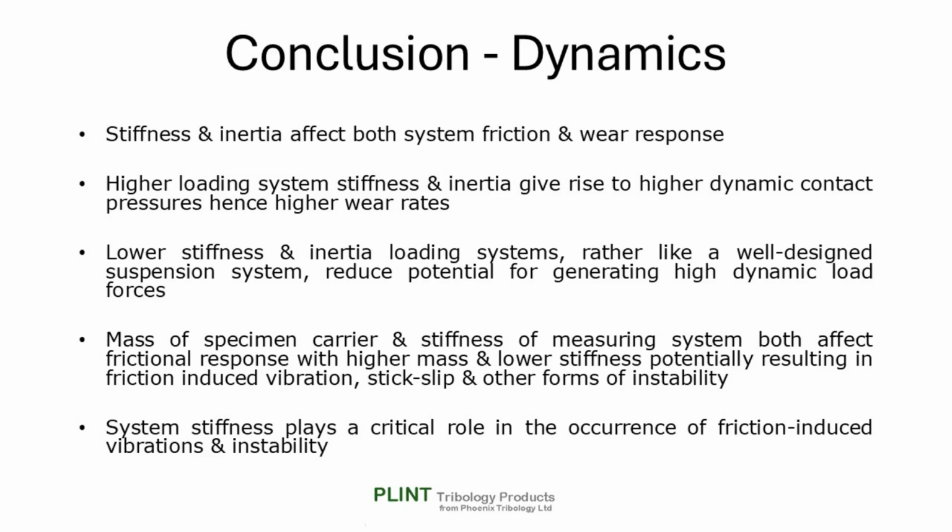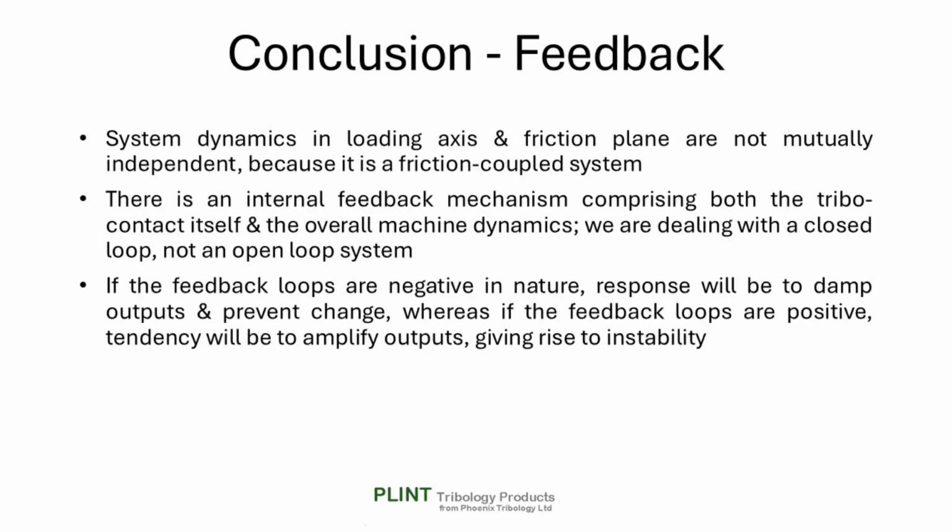When it comes to friction, the mass of the specimen carrier and the stiffness of the measuring system both affect the frictional response of the tribo contact, with higher mass and lower stiffness potentially resulting in friction-induced vibration, stick slip, and other forms of instability. We cannot, of course, afford to ignore force measurement, system bandwidth, and signal processing.